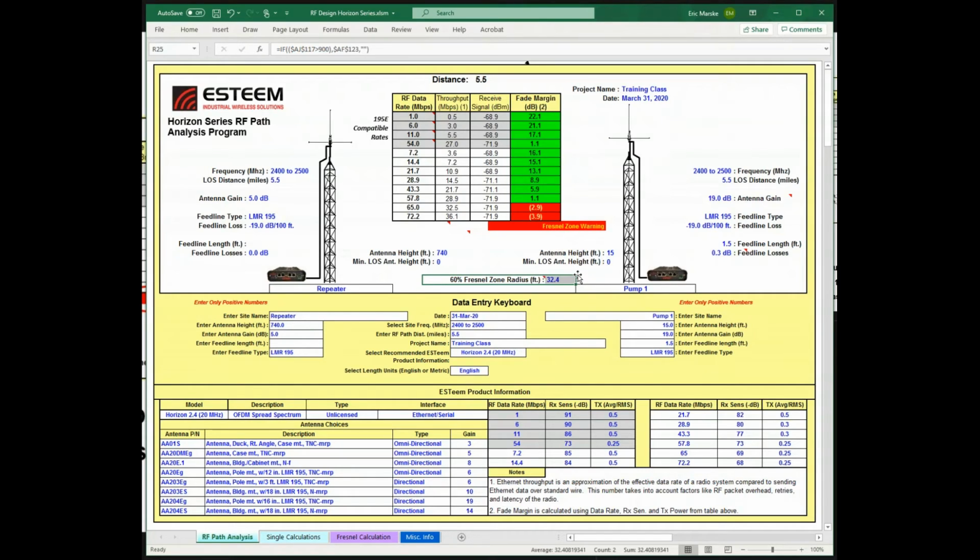What will happen then is that with the equipment being at 15 feet at the remote, we have a possibility that that system will cause a destructive reflection off the Earth's surface. Now, will it? We don't really know that until we go out and test it. But again, from the design side, we want to be as conservative as we possibly can, so we make the changes beforehand.